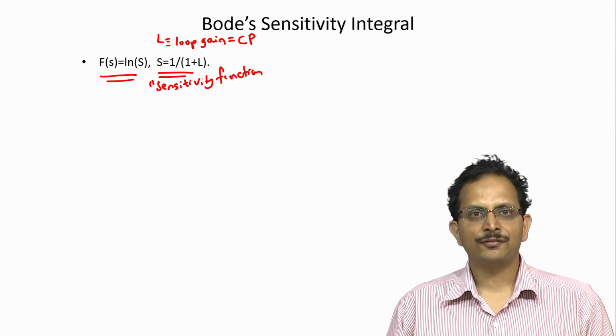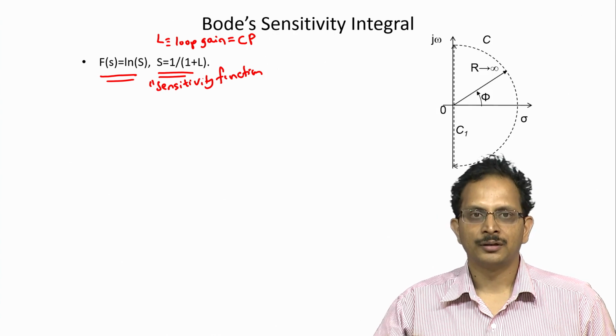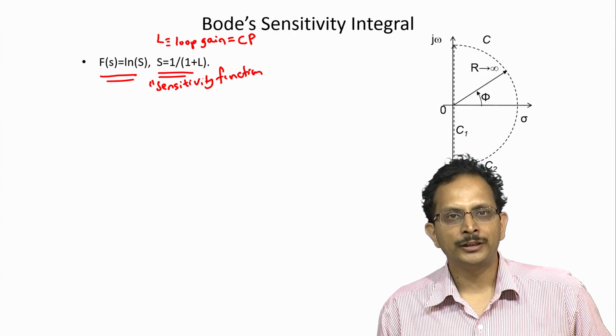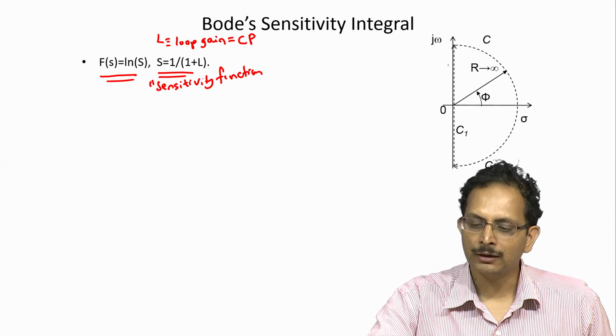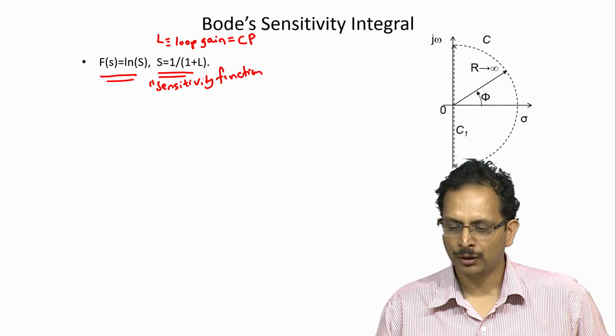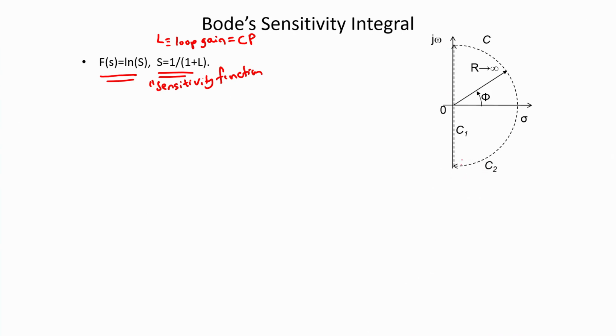Hence, if we define the curve C along which we would be evaluating the contour integral to encompass the entire right half of the complex plane, or in other words, the curve C is essentially this D shaped contour whose flat side coincides with the imaginary axis and whose bulging part has a radius r that is tended to infinity and hence encompasses the entire right half of the complex plane.